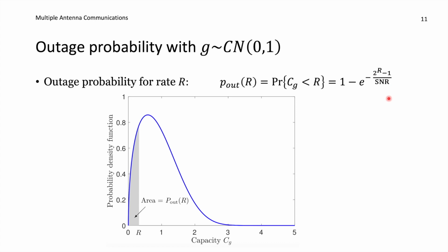And we want to operate our system at relatively high signal-to-noise ratios so we can communicate a lot of information. So in order to analyze even further what is happening at high SNR, well, if we have a high SNR here, then we have an exponent on e to the power minus the exponent here that is a small number. So we can apply a Taylor approximation that e^(-x) when x is small is 1 minus x essentially.